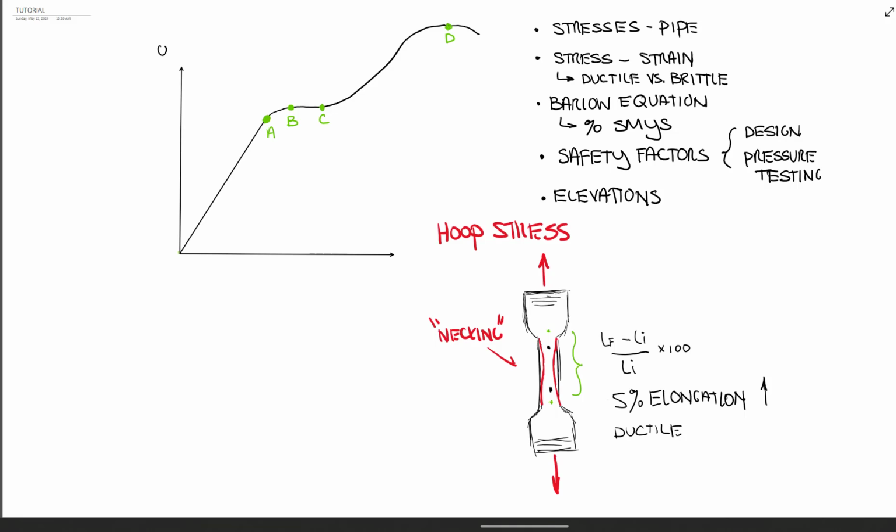Okay, so let's go over to our stress strain diagram. Essentially on the y-axis you have stress, that's signified by sigma, and it's in units of psi, another way of just saying pounds per inch squared. Stress over a specific area. And then on the x-axis you have epsilon, which is inches over inch, which is essentially dimensionless. And all this is saying is for the amount of stress that we put onto it, we're going to get a certain amount of stretch or elongation, or strain.